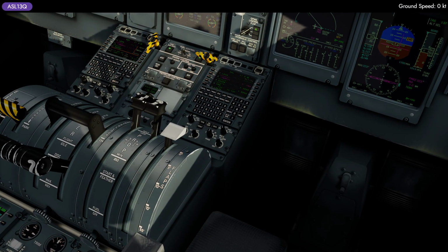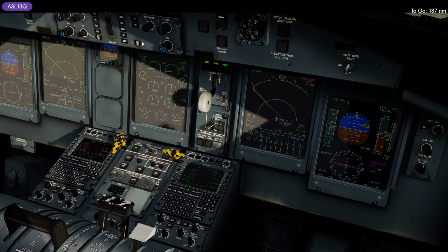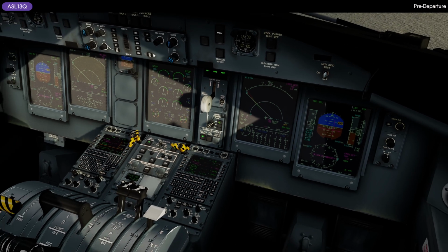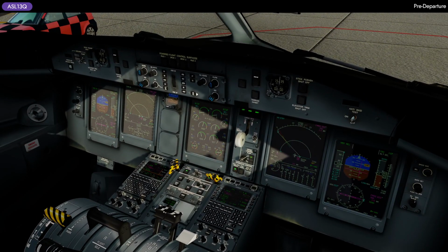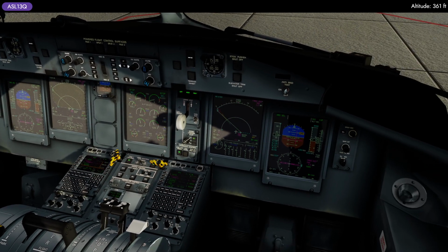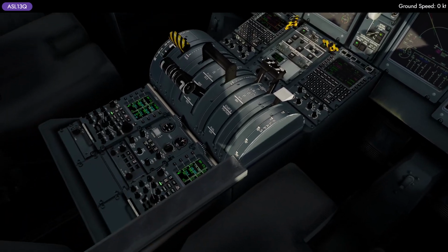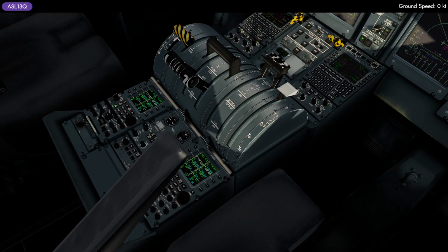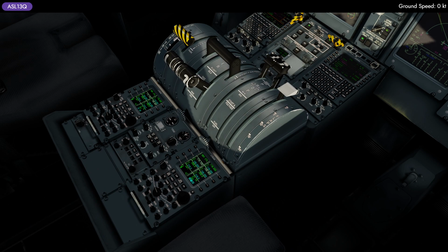Now go here. Our auxiliary fuel pumps should be on. The auto feather is also on. Standby hydraulic pressure pump also on. It's on. Turn on the yaw damper. Basically, one more thing. Since we are flying in uncontrolled airspace, we are going to slow to 2000.